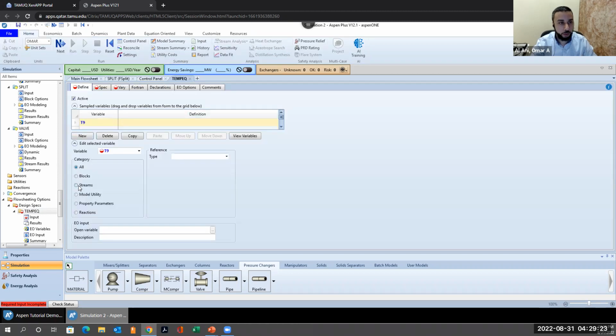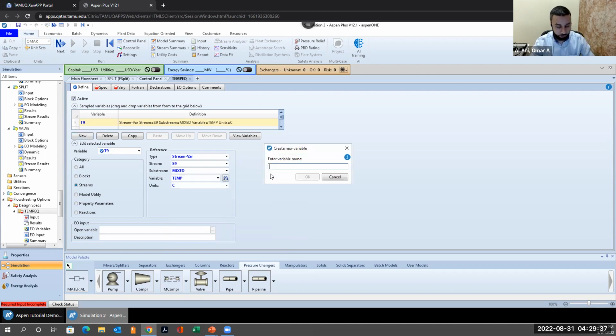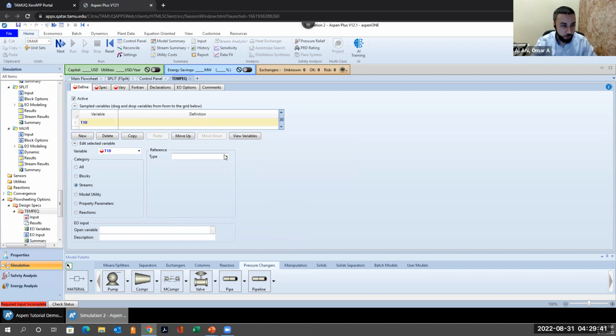Okay, and we can go to the streams, stream variable. We'll select the stream variable because that's what it is. We want stream 9, and we want the temperature. We can do the same thing for T10. So streams, stream variable, S10, and we want the temperature from that stream.